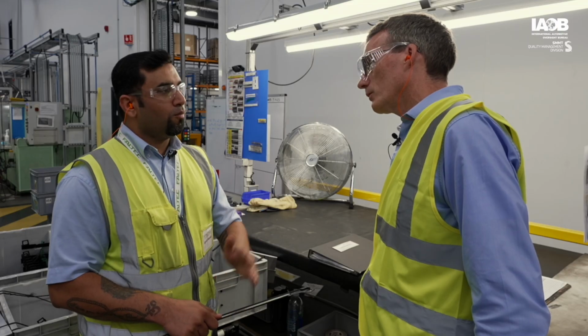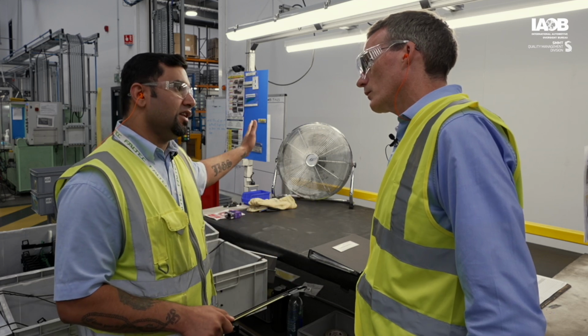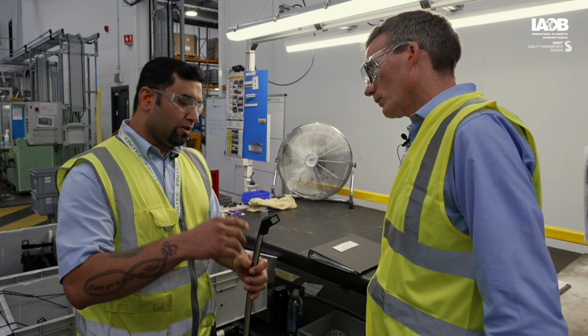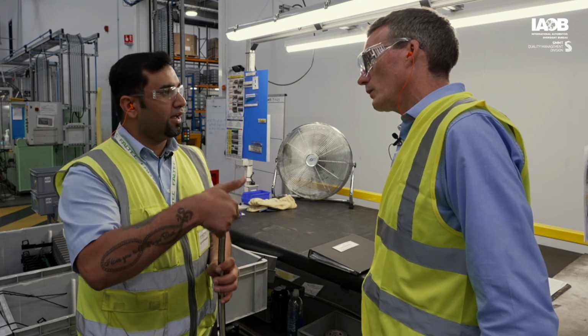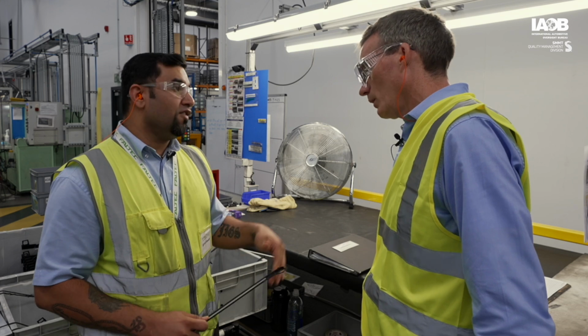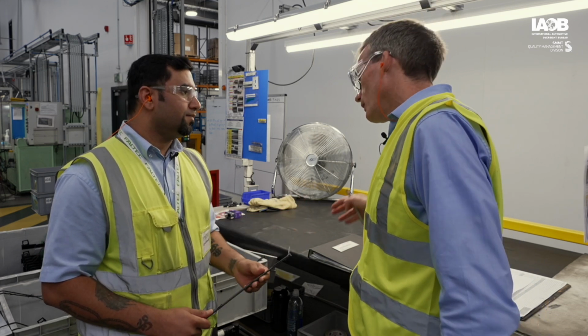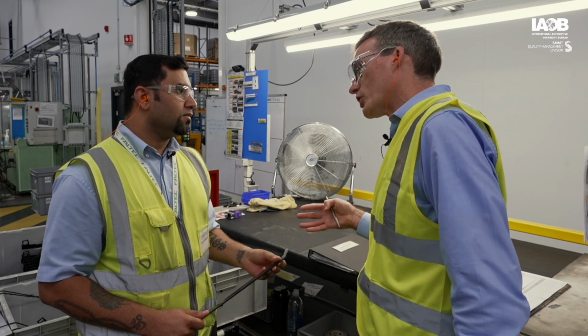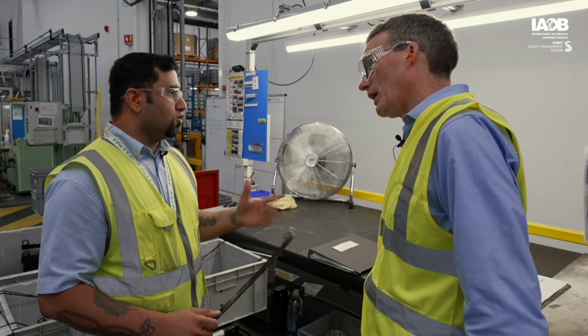If it doesn't come off, then we know the parts are good. If you want to go on a more thorough basis, we have a tensile machine in the lab. We cut the part out, use the tensile machine and put the force meter on it. The spec is 49 newtons. If it's more than 49 newtons, then our parts are all right, and then we refer back to production. And the containment check, is it a visual check? No, it is applying force.